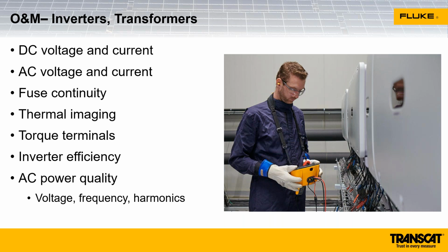One thing I want to point out here, this is a technician using our SMFT 1000. This may look like an odd installation to those of us who work in the United States, but this is a commercial installation in Europe. So they have different code requirements there, and using conduit is not a requirement there. So that's why we see all those conductors hanging out at the bottom of the inverter there.